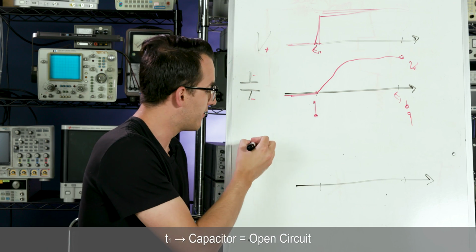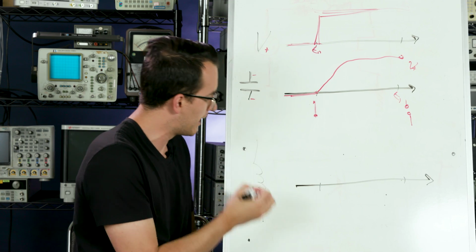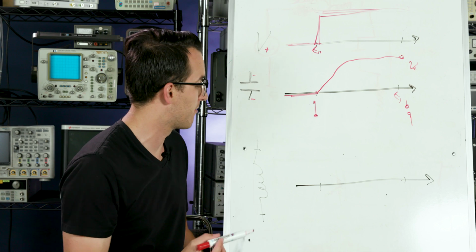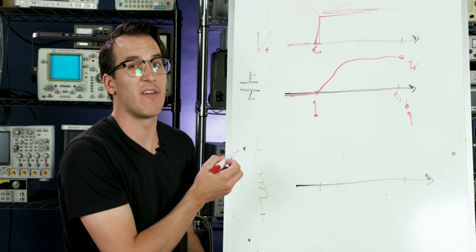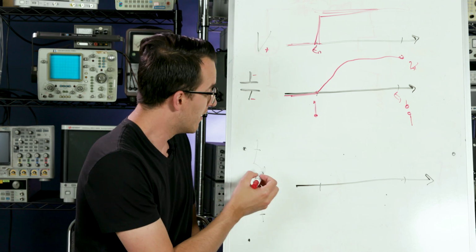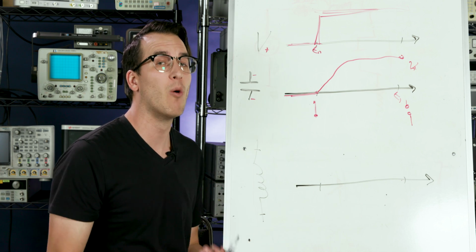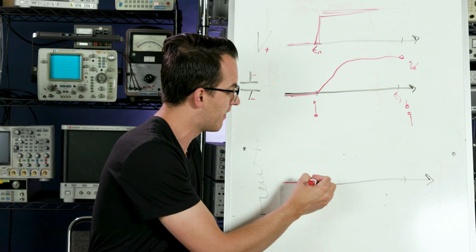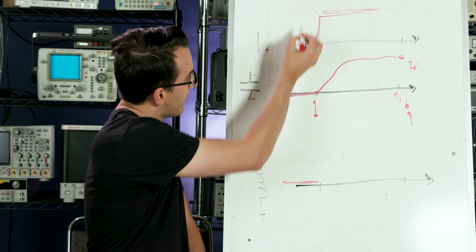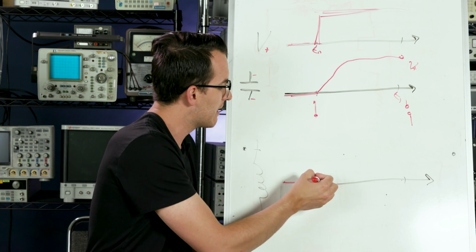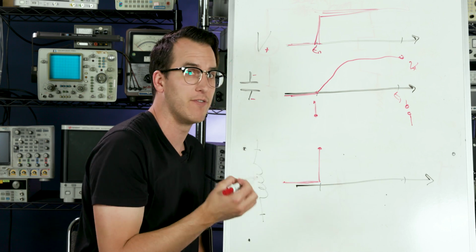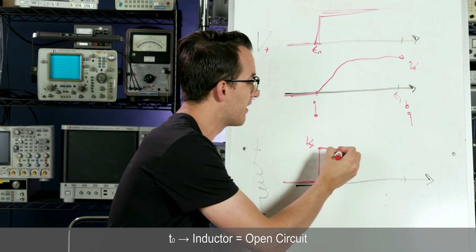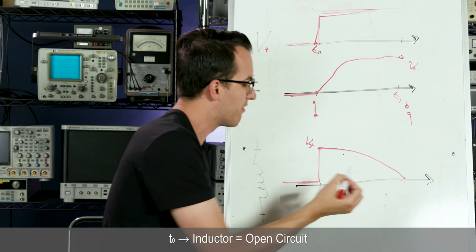And next, let's look at an inductor, and we draw it with this little squiggly line here. And we're going to look at the voltage across the inductor as we get a step response from our voltage. And an inductor is essentially the opposite of a capacitor. So it's going to start actually as an open circuit. It's going to resist a change in current. So at time t equals 0, we still have 0. But as soon as the step turns on, we're going to get pretty much a spike right up to V+. And over time, that's going to decrease down to be about 0 volts.